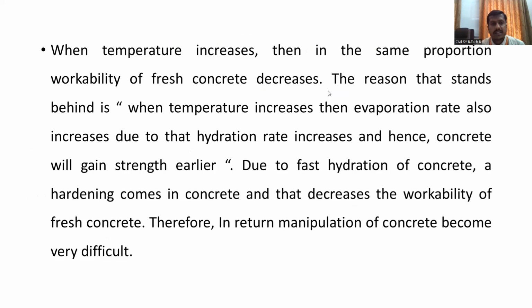Okay, the reason behind this is that when the temperature increases, the evaporation rate also increases, and due to the evaporation, whatever hydration process is going on will increase and the concrete will gain strength earlier. But due to the higher speed of the heat of hydration process, hardening occurs in the concrete, and that decreases the workability of the fresh concrete. Okay. So in return, manipulation of the concrete becomes very difficult for us.